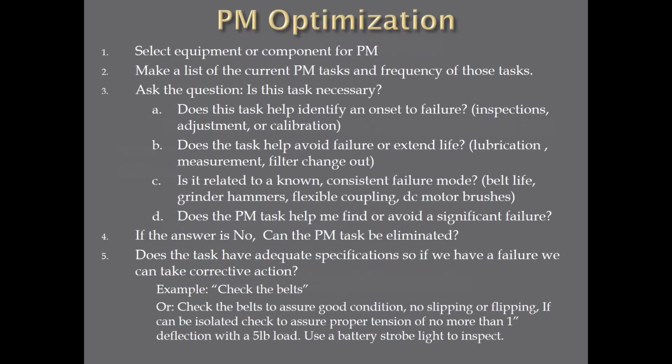Now, I can send you this if you want this. Just let me or Justin know. I'll send this to you in a Word document. I'm trying to get my programmer to make a database up, something like my RCM database for doing PM optimization. But this is what I usually do: I have this Word document and I make a list of the PM tasks I'm currently doing, and what are the frequencies of those tasks? And I start asking questions.